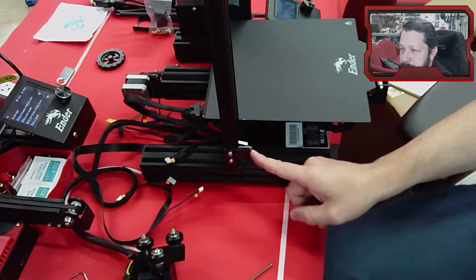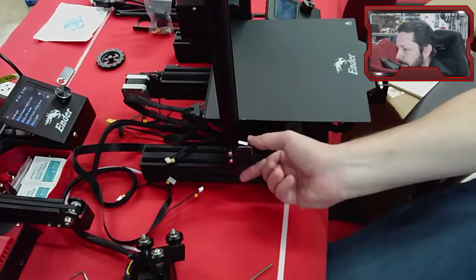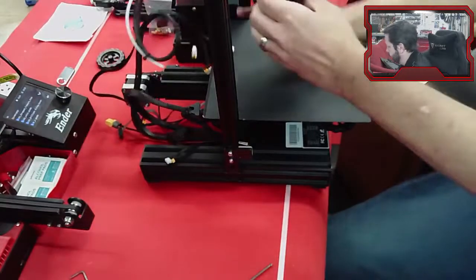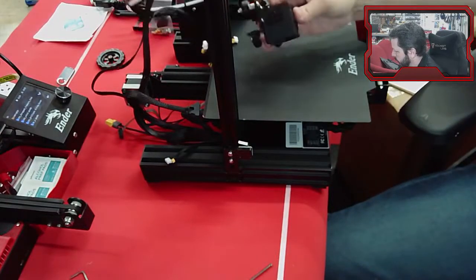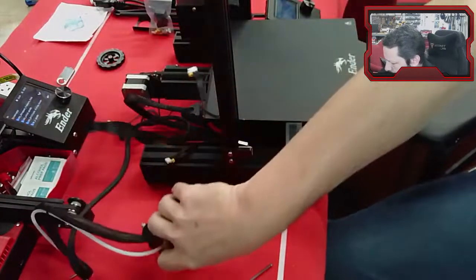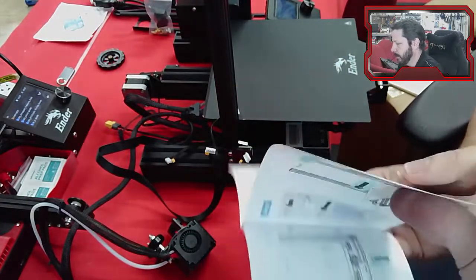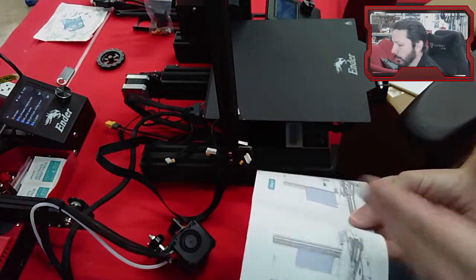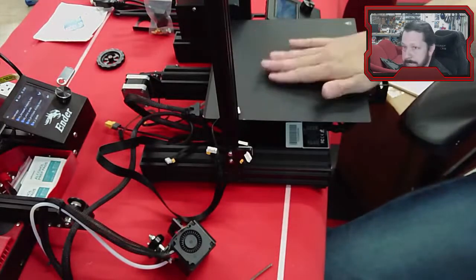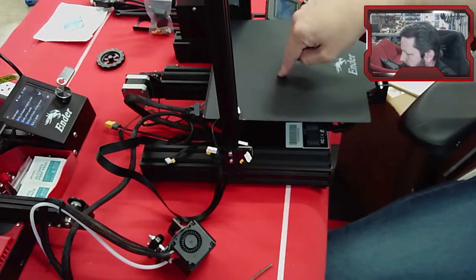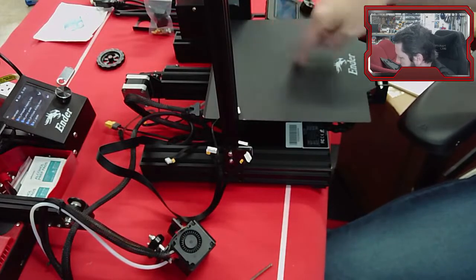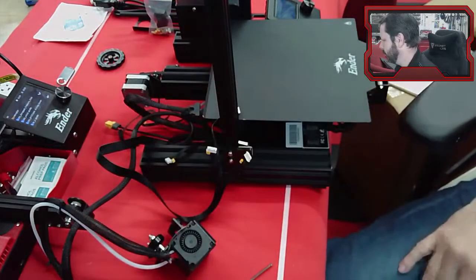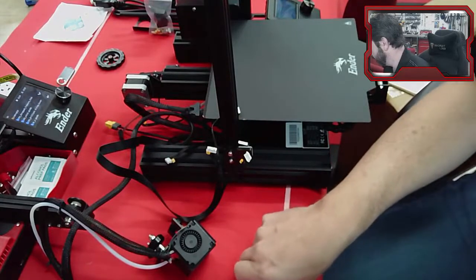Now this we will have to come back later probably and adjust the height of this so that our Z or nozzle is the right height off of the bed. You want the nozzle to be about, this is thin paper, but the thickness of maybe 2 of these sheets of paper or 1/5 thicker sheet of paper off of the bed. If it's too close, then it can't spit filament out. If it's too far away, then it's just dropping filament on the bed and it's not sticking. We kind of get the kind of problems we had over there, although that was something else. We'll get a good print. I'm not too worried about that.